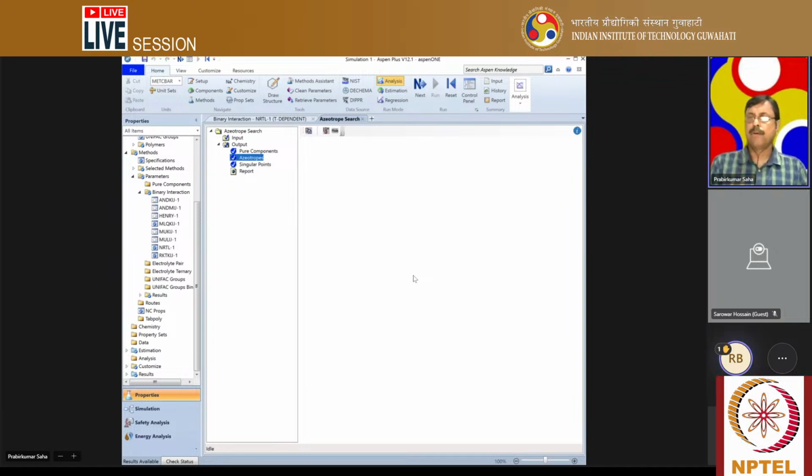Okay, so in your ternary data, is LLE there? Yeah, in the ternary data, sir, LLE is there, but I don't know how to regress this combination of VLE and LLE data. So in this situation, you feel that probably azeotropic distillation is not possible. Okay.